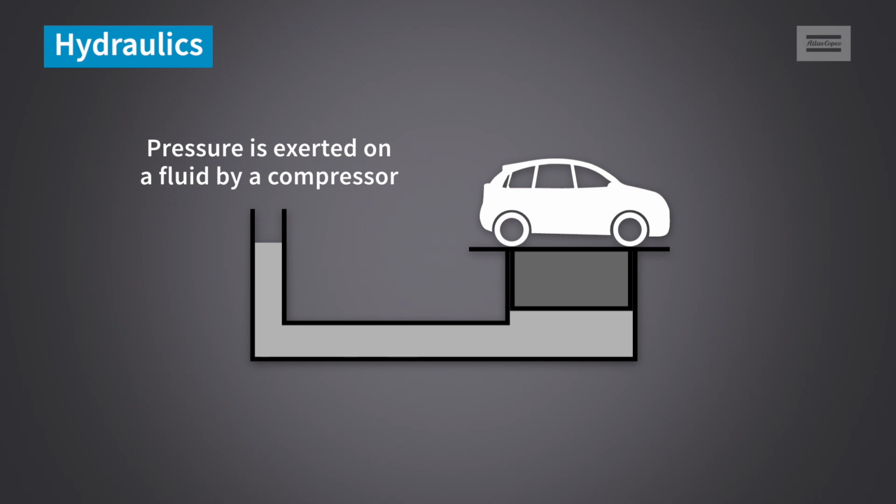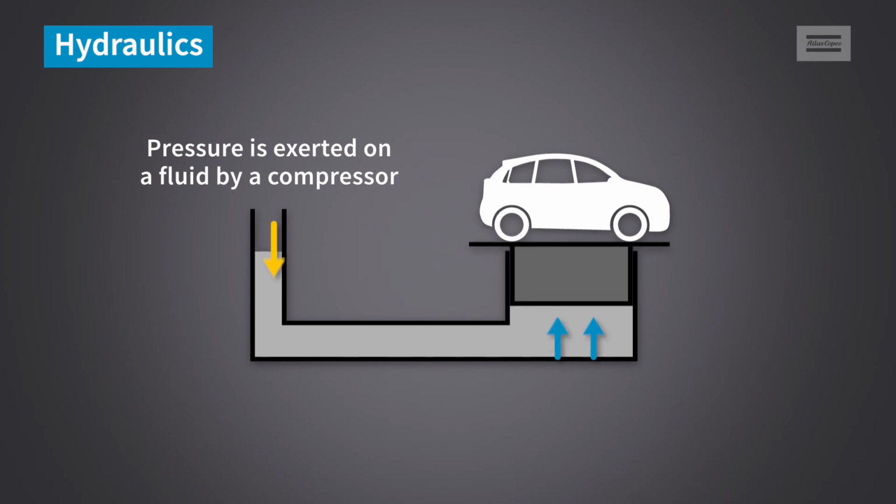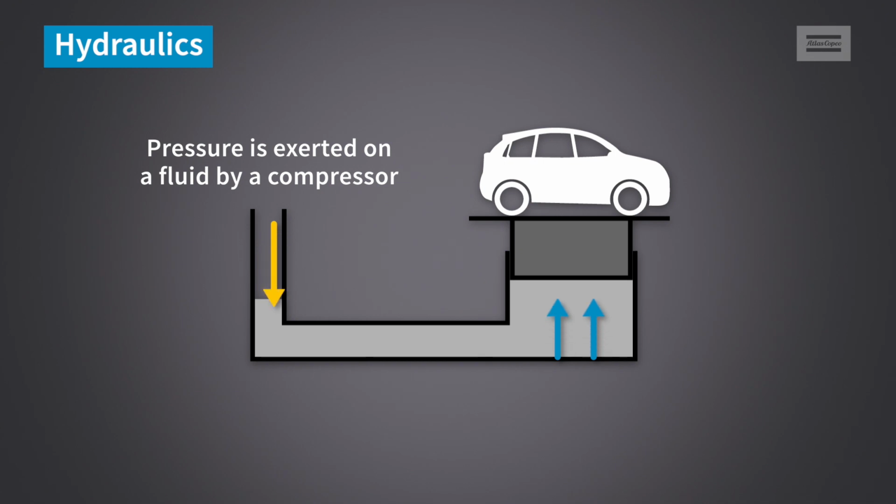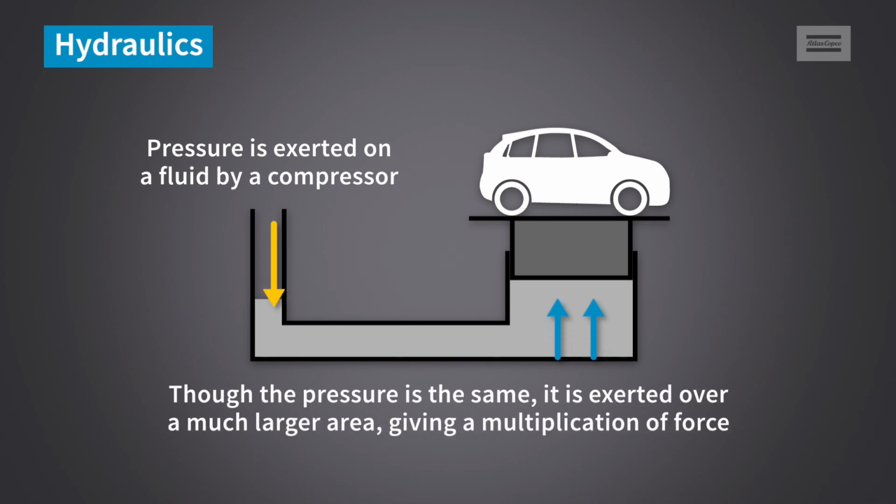The pressure is created via a power pack, which is exerted on a fluid in a small area. This pressure is transferred equally throughout the fluid, and although the pressure is the same, when exerted over a large area, it multiplies the force, giving the ability to move greater objects.